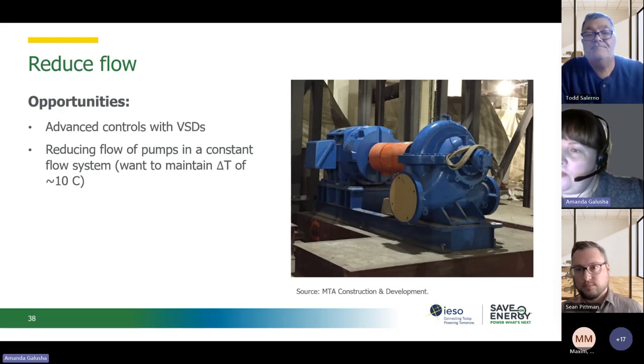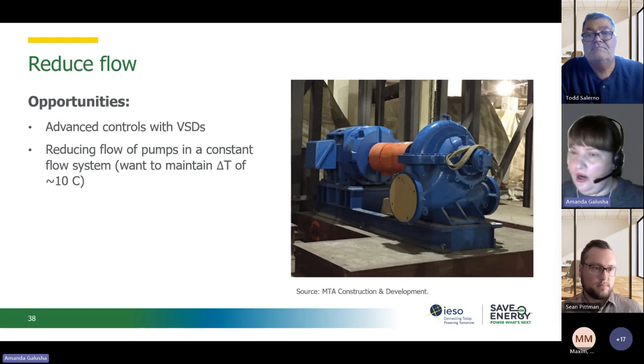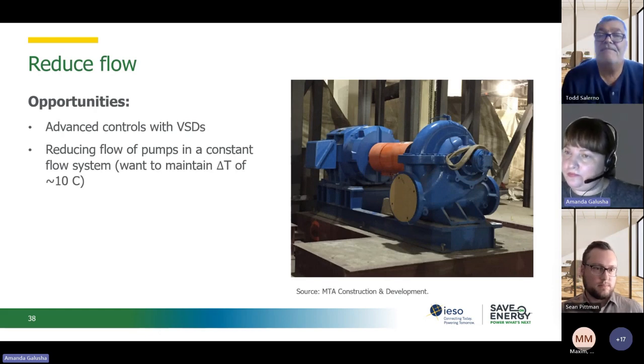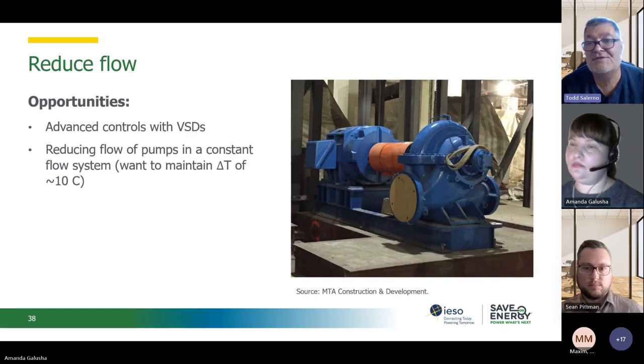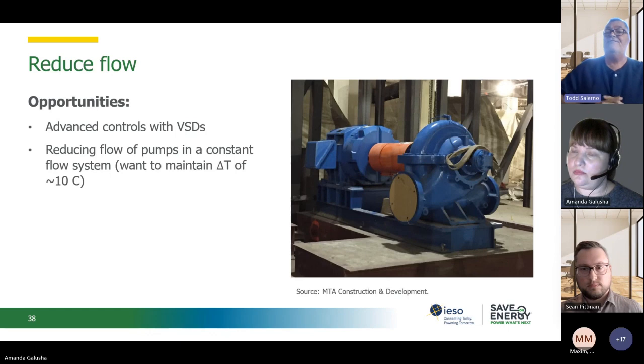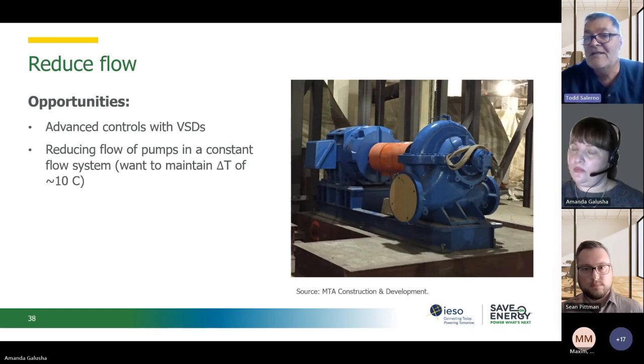Todd, are there any risks with reducing too far? Well, yeah, because you have your chiller, which is designed for a certain flow, and then you have your system. You have to make sure that you're pushing enough water through your system to provide the cooling to the end use. So yes, there is potential risk with that. It's not necessarily cut and dried. You have to look at the whole system.